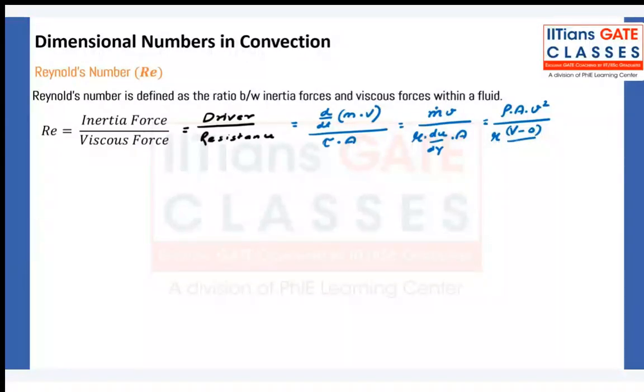So we are going to say dimensionless L or D into area. Now we can cancel velocity. Okay. So rho A v square upon mu v area by d. Okay, velocity and velocity get cancelled, and finally you will get Reynolds number is equals to rho v d h, this is your characteristic dimension, upon mu.